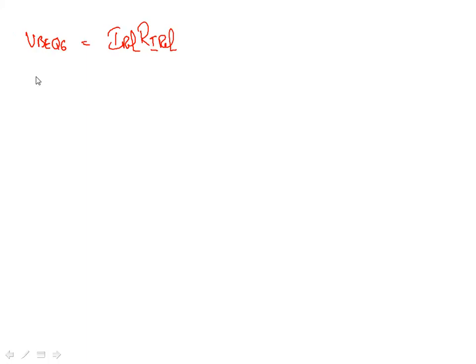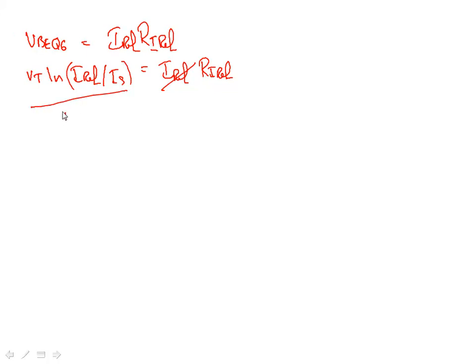Okay. VBE Q6 is VT natural log I ref over IS, is equal to I ref R I ref. Divide by I ref. We've now found R I ref. So let's put some numbers in.